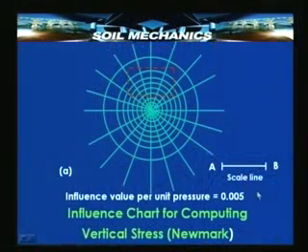This chart has been plotted for a depth scale given by AB equal to z. Therefore, in order to use the same chart for all depths, all that we need to do is always take the length AB of this chart as equal to the depth.